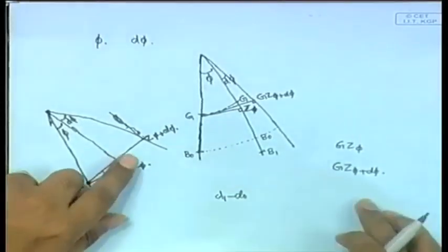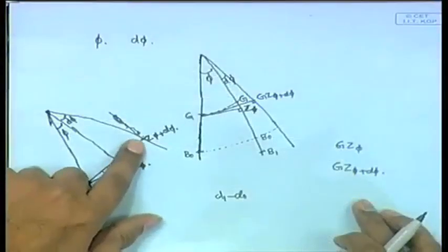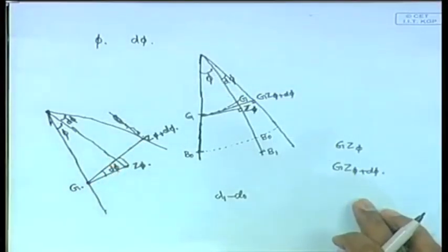We draw a water line through this, that water line is horizontal, though on the curve it looks inclined, it is actually horizontal. The perpendicular to that water line, which is the line through B, will always be a vertical line. So, just like this is a vertical line. So, the distance between this point and this point will give you d1 minus d0.